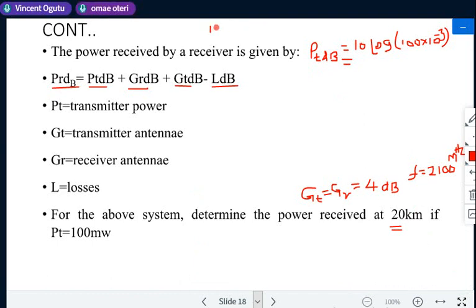Yeah, usually when you are calculating power in terms of decibels, you need to use 10 log always. Whatever value that you have here, if it's power, it will be 10 log. If it's voltage, it is usually 20 log, and current. So it's a constant. It's just something which is a standard. When you're changing from the actual values to decibels, this is what you use.